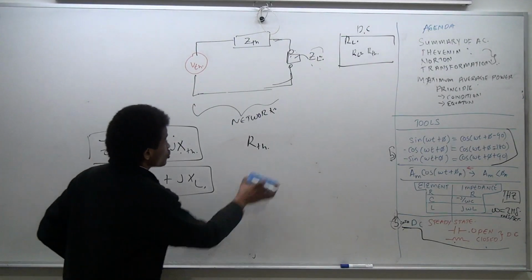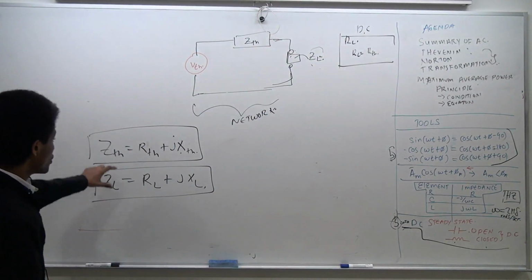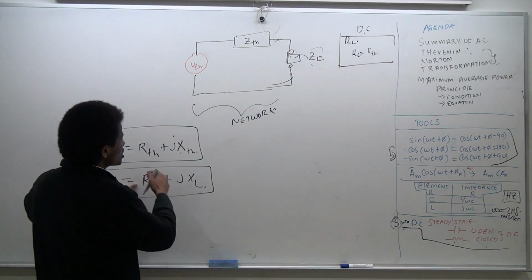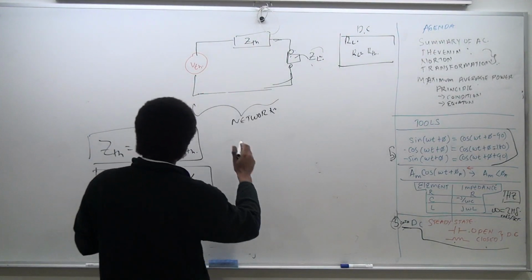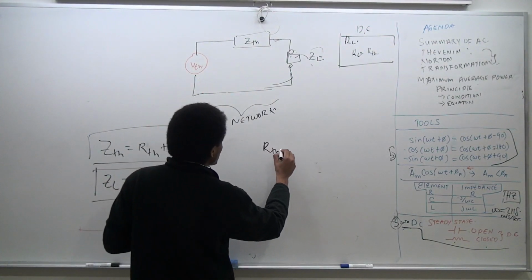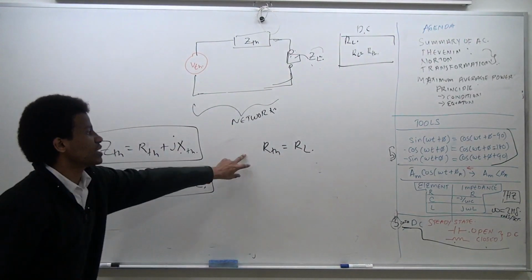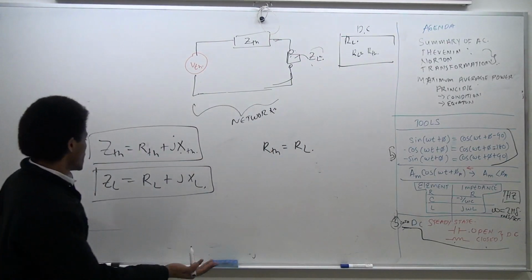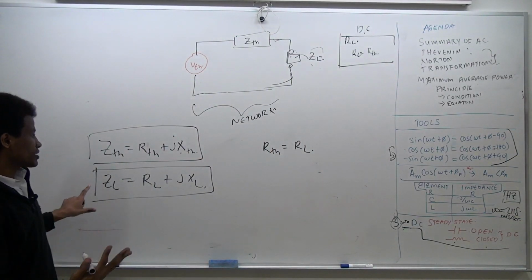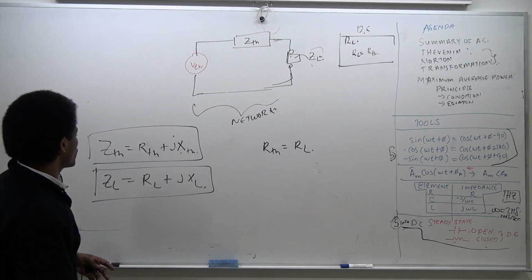Now the question is, when you solve this two-dimensional optimization problem, you find out that the DC case still holds. To maximize power transfer, you have to have R Thevenin equal to RL. This is the first step, and it's consistent with the DC case. But under the AC case, we're dealing with a complex number, which is a two-dimensional sort of entity.